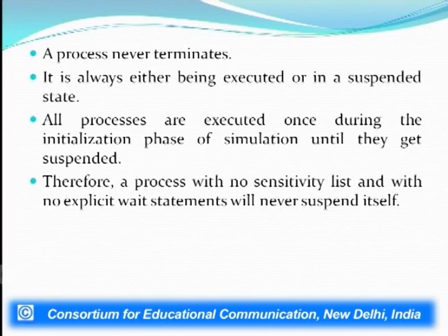So all the processes are executed at least once during the initialization phase of simulation until they get suspended. Therefore, a process with no sensitivity list and with no explicit wait statement will never suspend itself. It will go into an infinite loop and it is not going to be suspended.